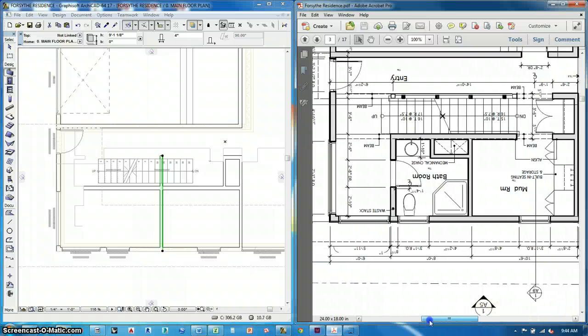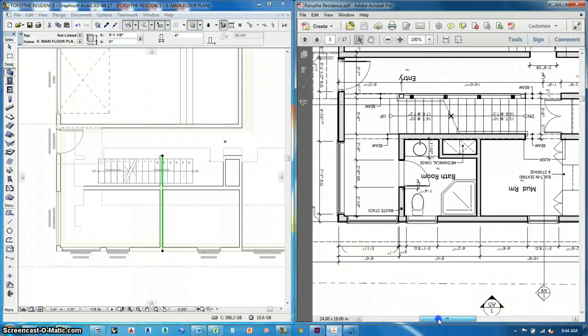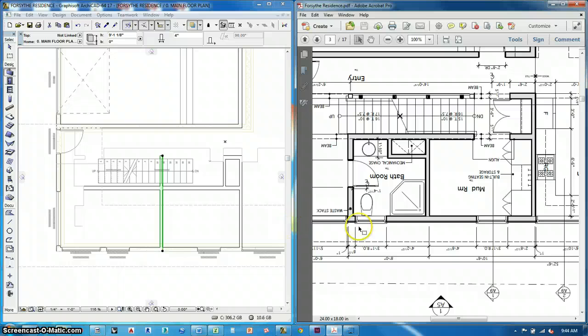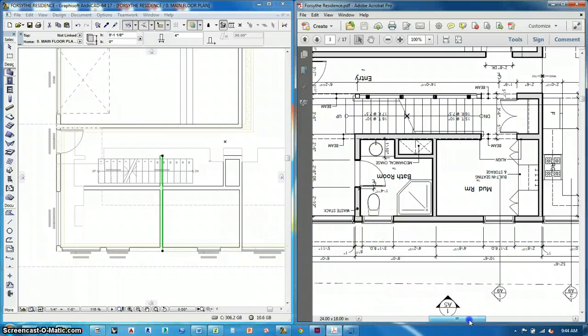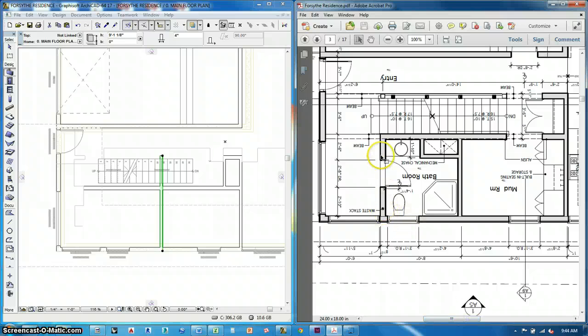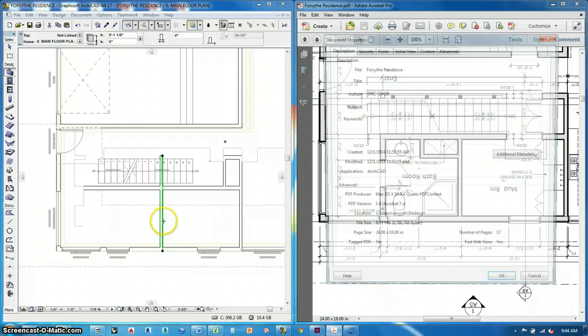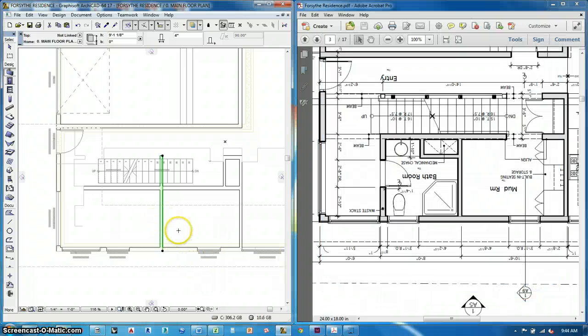It might be that they were trying to control a dimension here, but it doesn't really look that way. It just looks like it's sort of not worked out very well. It also looks like they're sneaking a waste stack into this wall, so this wall would have to be a 6-inch wall as well. Any wall where you have some plumbing against it would need to be a 6-inch wall. So I'm gonna drag this 8-foot, oops, wrong window.